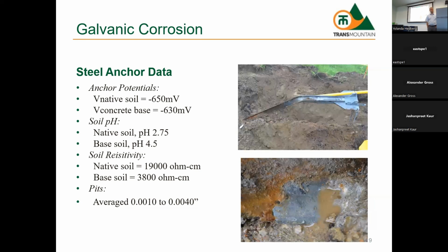So I thought we designed for like 20 or 30 years, but do we still need to do the inspection every year? Or for example, after installation, you just check after 5 or 10 years? So if it's a regulated pipeline, you are mandated to check it every year. If it's not, if it's a water pipe or a communications tower, you're not mandated to check it. But you should, obviously. The design life for a magnesium anode for something like this is going to be like 15 to 20 years.